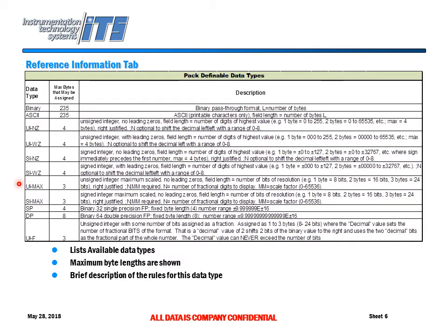And then you have signed and unsigned max. Now the max indicates that the value is scaled. The scale is relative to the full scale value of the bytes, not the source. So if you have 255 bits, meaning a 1 byte signed integer, you have 127 bits of value. So at 127, you can assign that to some value like 300.